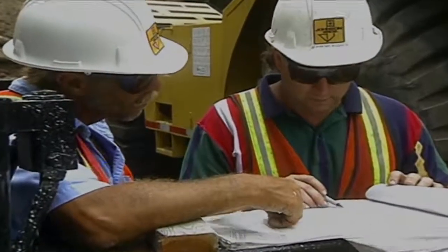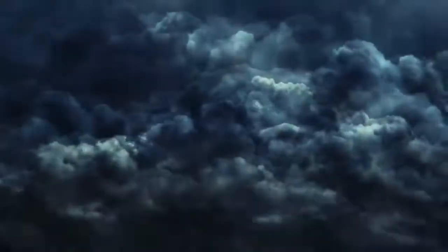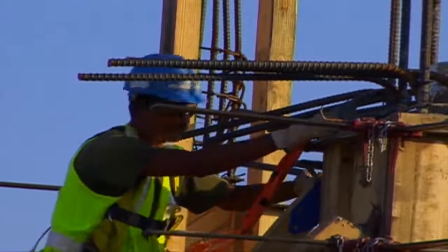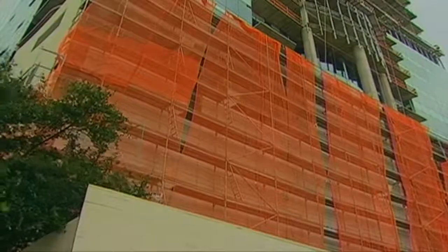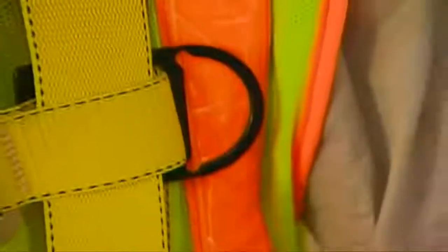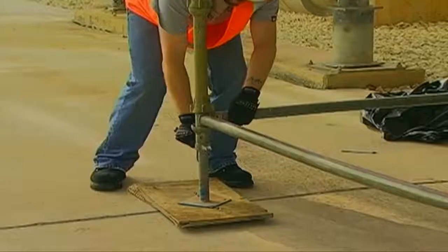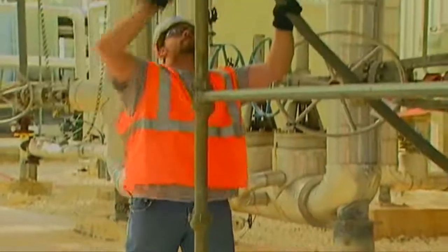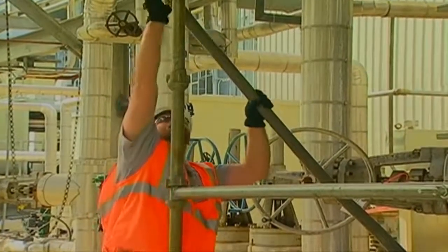A competent person is to determine if it is safe for employees to work on or from a scaffold during storms or high winds. Other competent person duties include ensuring that a personal fall arrest system or windscreens protect employees, and to determine the feasibility and safety of providing fall protection and access for erectors and dismantlers. The competent person must also make sure that a scaffold will be structurally sound if intermixing components from different manufacturers.